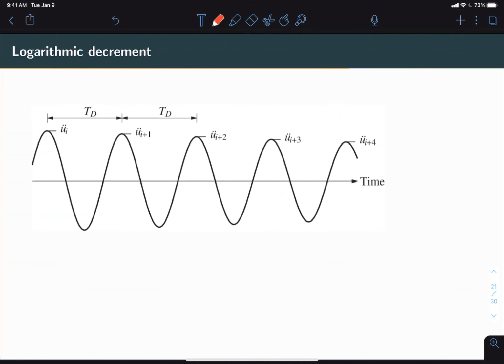Now in practice, there usually is no way to measure damping directly like we can do with stiffness and mass. It's quite an elusive parameter. And so the best way to do that we have is to get the system into free vibration and then simply observe the decay and try to quantify what the zeta is, what the damping ratio is. And one way to do that, at least with single degree of freedom systems, is the logarithmic decrement technique.